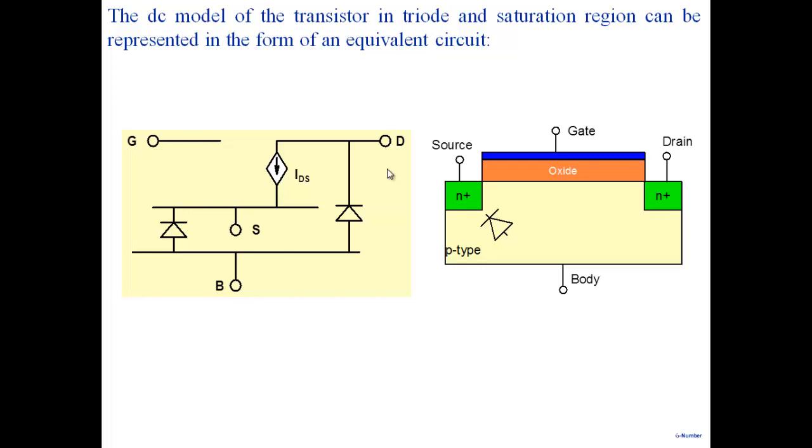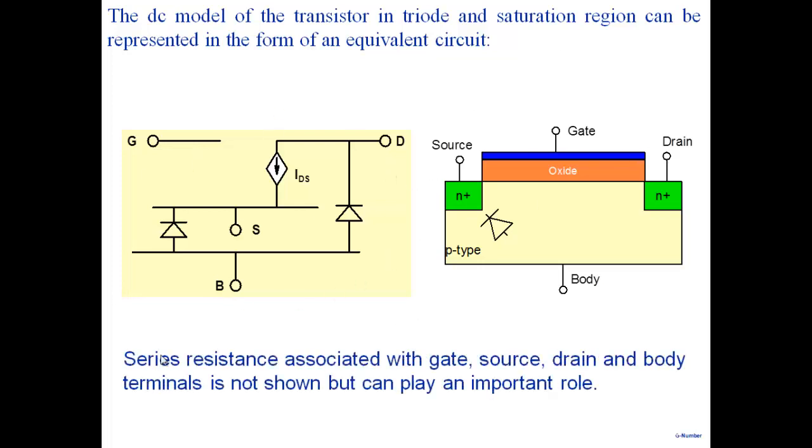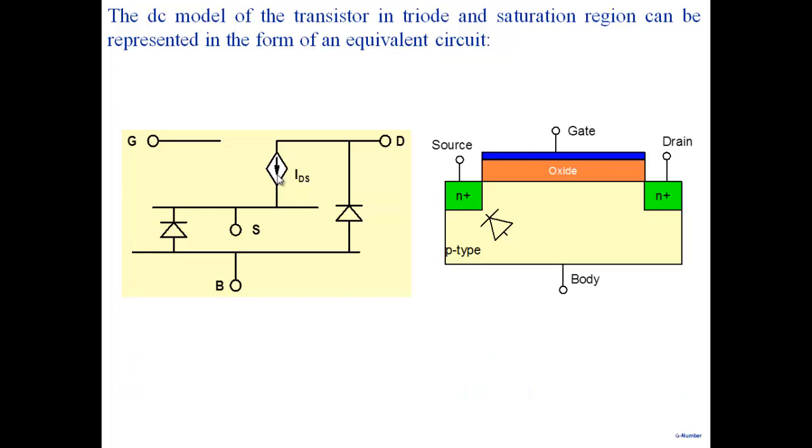Okay. So if you want to think of a MOSFET, if you have a circuit and it's a DC circuit and you want to analyze, then this is what it is, a MOSFET here. And we have expressions for current. So all you have to do is decide now, is my MOSFET operating in saturation region? We have an expression for current in saturation. Is it operating in linear region? We have an expression for that. Is it operating in subthreshold? We have an expression for that as well. Right? So you have to decide which mode the transistor is working in and apply an appropriate expression for current, and then you have a first order description of how things are happening in the MOSFET here.